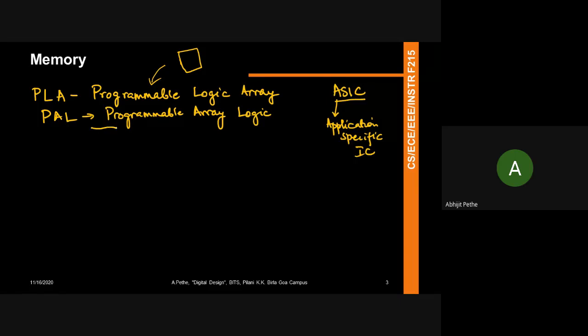So what this allows you is basically you can design any combinatorial logic from this generic chip that you buy by using what are known as fuses. There are electric fuses available inside this chip, which you either blow or let them remain. With that, you can buy this chip from the market and program it once to make it into the combinatorial circuit you want. Right. So these are generic, hence they tend to be very cheap. I mean, they're less than a cent. You can go buy it and use them any number of times in your chips.